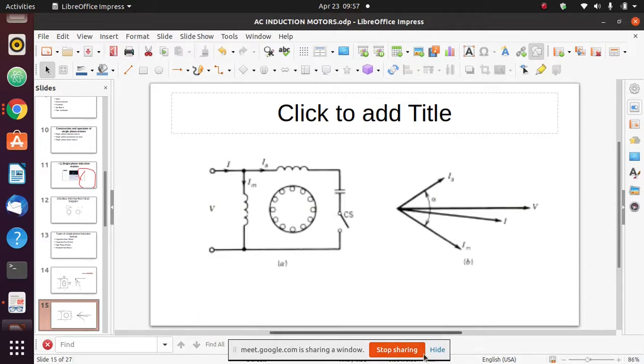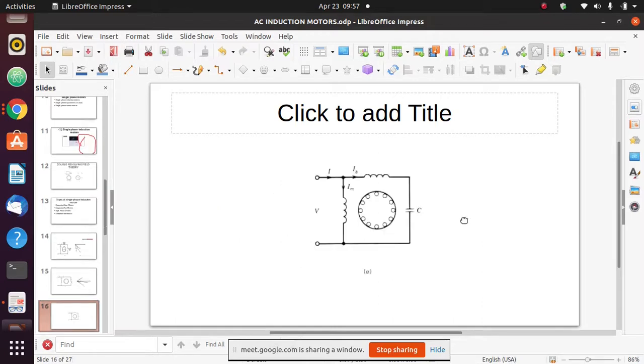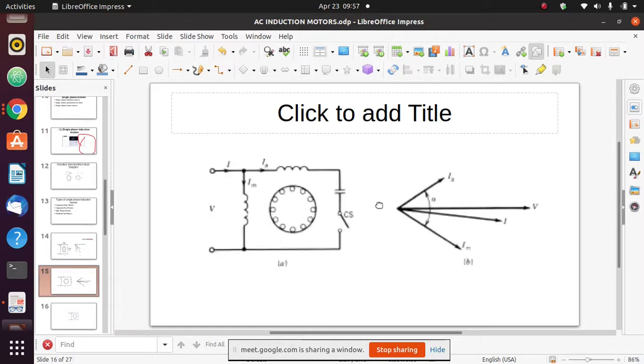The disadvantage of this is the high cost; it will be expensive. With a high phase angle, the motor will have a high starting torque, so use it for high starting torque applications. Now, in capacitor start we have a centrifugal switch.